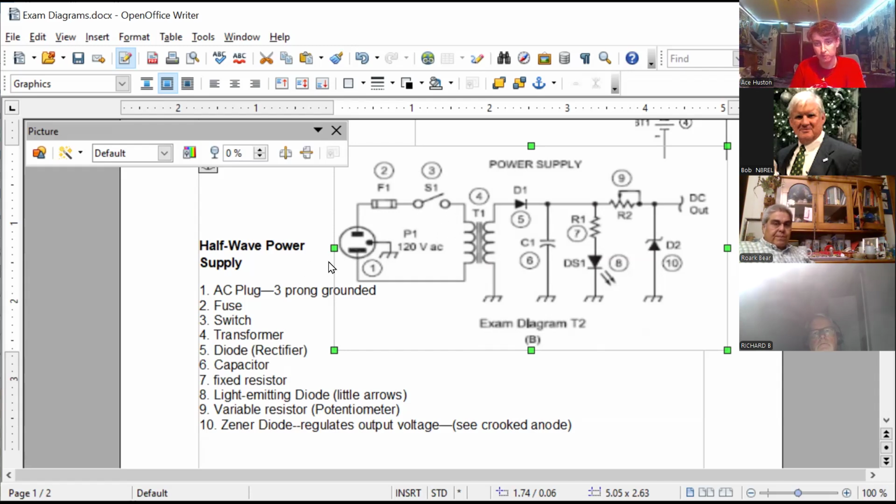This is a standard United States plug or socket. This would be the plug. The small contact is the hot one, and that's also the black wire. If you open up your wall plate, you'll see a black wire, a white wire, and either a green or a bare wire.